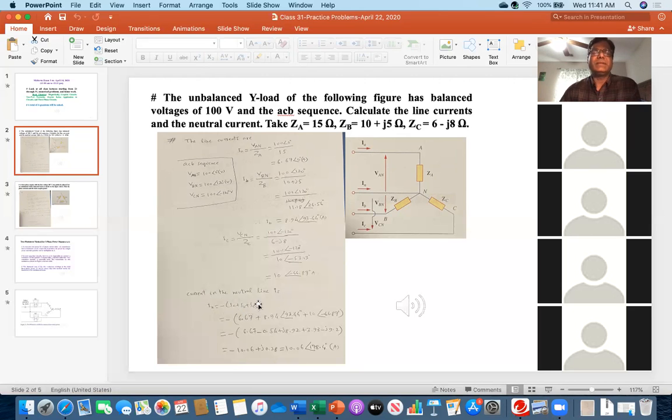And then you just plug in those numbers that you calculated, IA, IB and IC. And then this is the result. So you can see this means that the neutral has 10 ampere current. It's a good amount, a significant amount. So if for a long time this current flows, then that neutral line might be overheated and might be damaged. So that's why an unbalanced system is undesired.